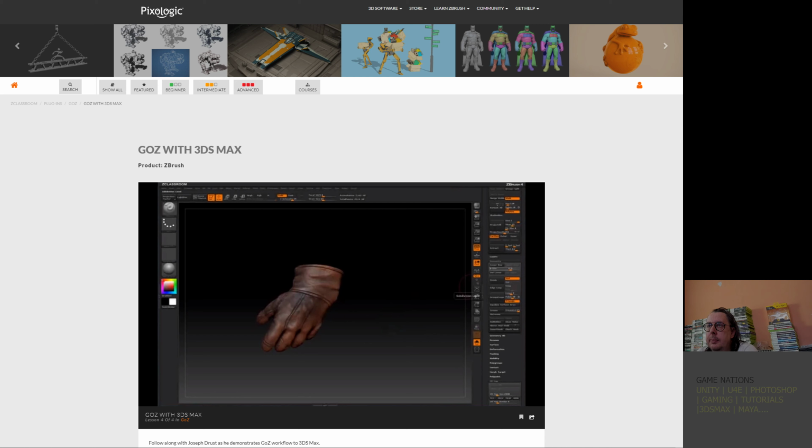To do this, we're going to scroll down to the first subdivision of the model and see we have a polygon mesh that's about 145 points. Now this is a little bit low for bringing stuff in and then using it as a displacement mesh. It's going to give you a little bit of issues with just how low polygon it is. So I'm actually going to take this mesh and go up to subdivision 2 and then delete lower. Now it's a good habit to do this across all your tools. This just gives you a little more resolution for when you go inside of Max, and it will help your displacement map project a little better.